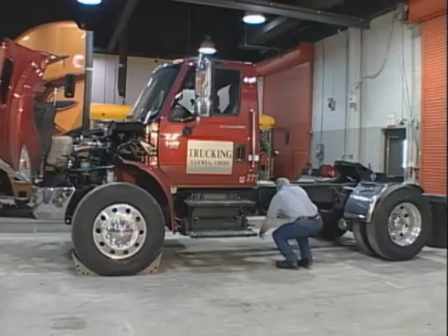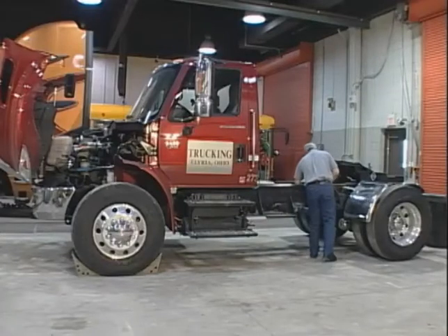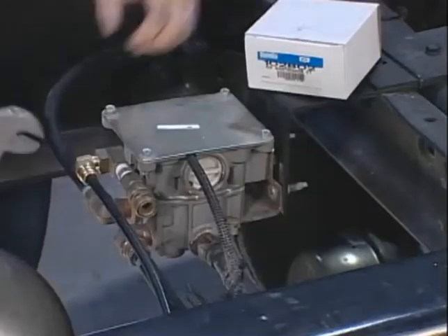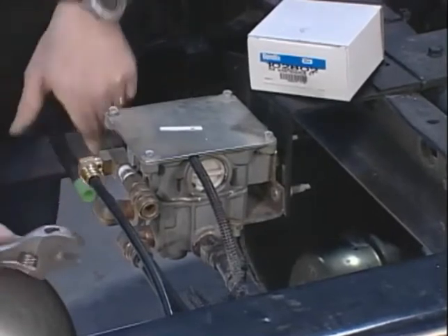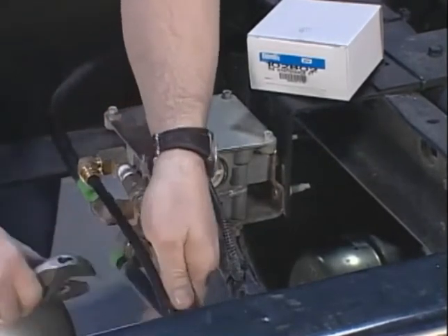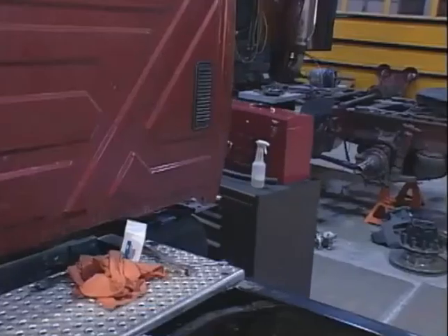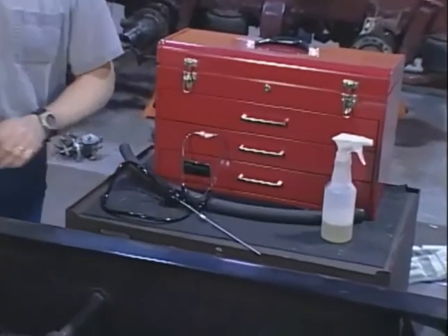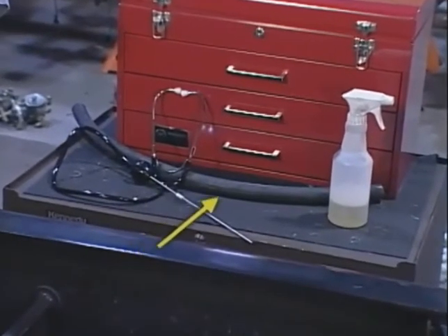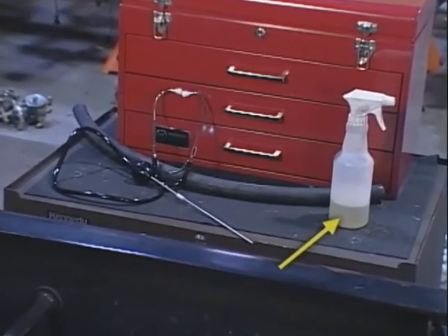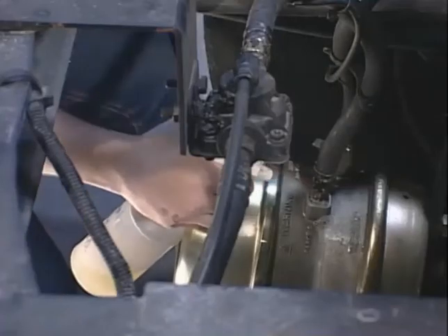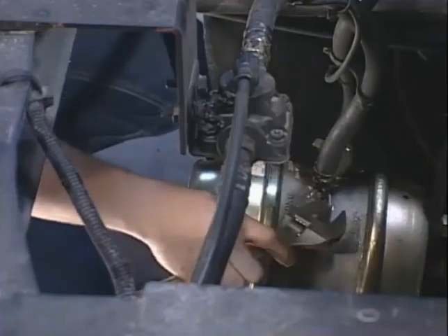In addition, you might be dealing with air leakage from other sources, say from fittings or valves. And depending on the possible cause of the leak, that type of leakage might call for everything from no action to a simple tightening, to a repair or replacement of system components. So since it's obvious that location and size both affect the course of action, we'll look at both concepts at the same time. The good news is you probably already have the recommended real-world tools for both. And whether you use a mechanic's stethoscope or a hose to pinpoint an audible leak, or a soap spray solution to find the source visually, you also need to know whether the leak you may find requires immediate corrective action.